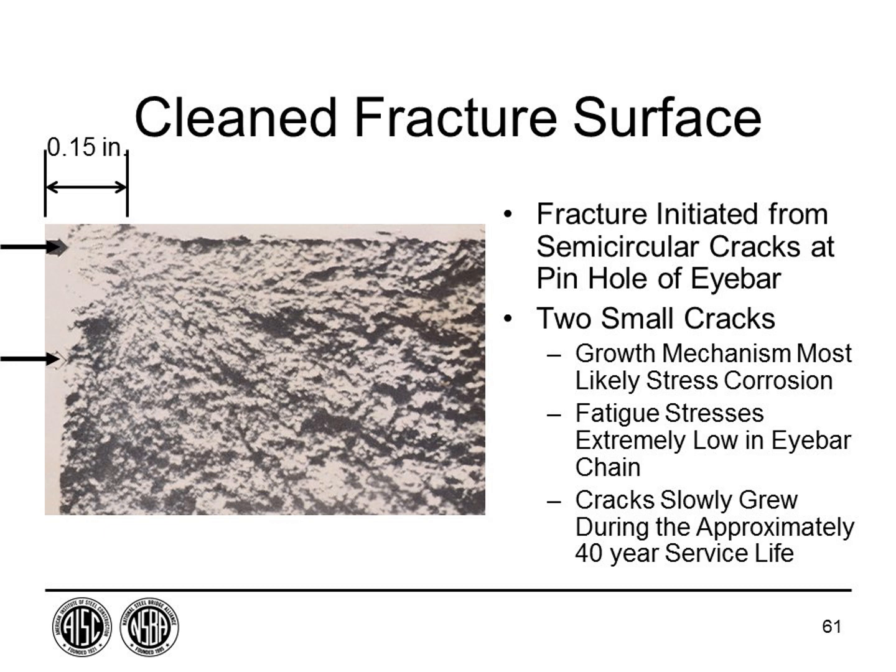And so the lesson that we learned from this is that what we need is material that can tolerate larger cracks. There's no way that we could find this crack in an in-service inspection. In fact, there was a sister bridge down the river made of the same steel. They attempted to inspect it, but they were unable to reliably find these small cracks, and so the bridge was taken down.